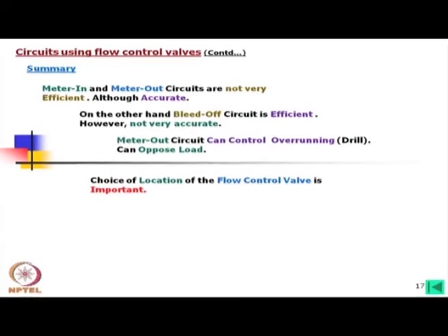If you look into planer machines, the purpose is different. If you look into shaping machines where the tool head is moving, it is different and the load will also be different. In the case of drilling, if the feed increases, then more load will be experienced, particularly at the time of breakthrough, when the drill is finishing.